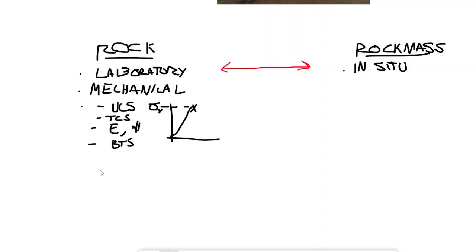And we could repeat that over and over in a very scientific process. This is standard, what you learn probably going back to 3rd grade, right? You can take a bunch of different samples and record them and say, okay, we got some data here. Maybe some of the time it fails around here. Maybe some of the time it's much stronger with all these different samples. This will be our UCS on the x-axis, and this will be our frequency N on the y-axis. And you could develop summary statistics from that, say x bar and sigma, to use traditional probability and statistics symbols. And once you know this, you can use that to predict things about the rock.